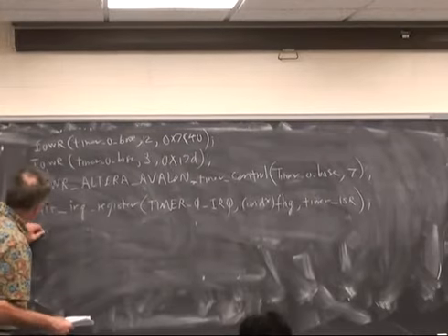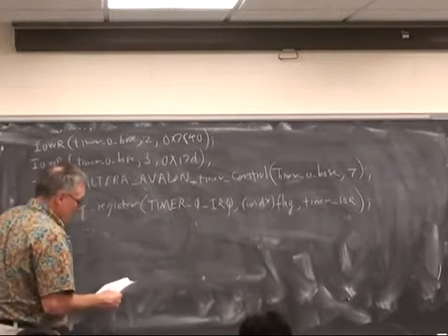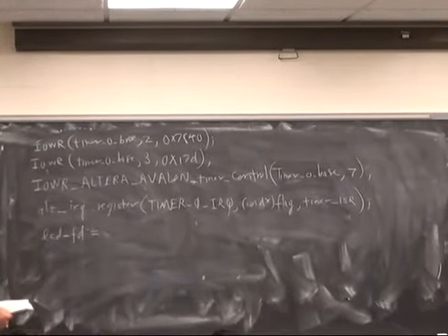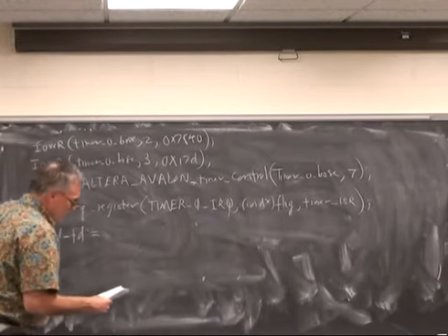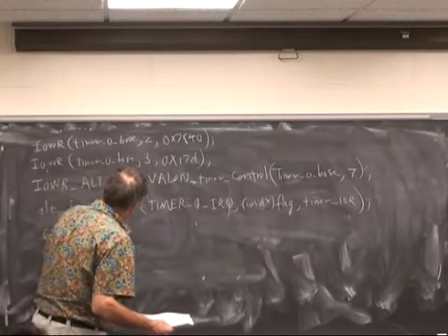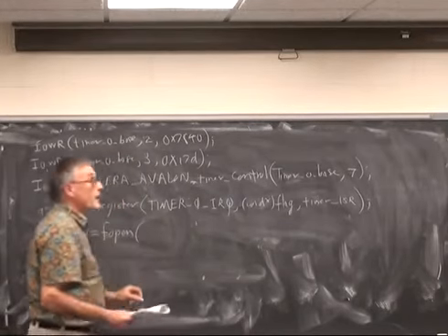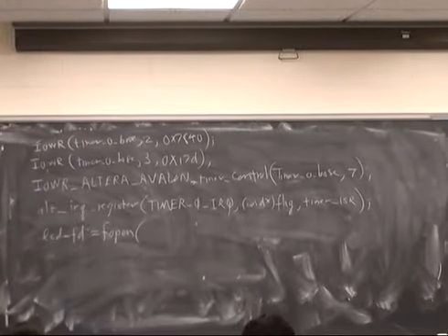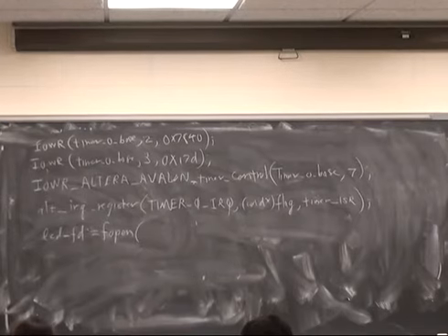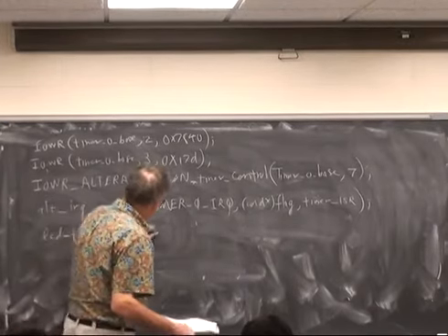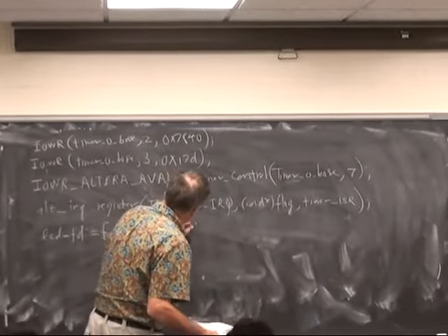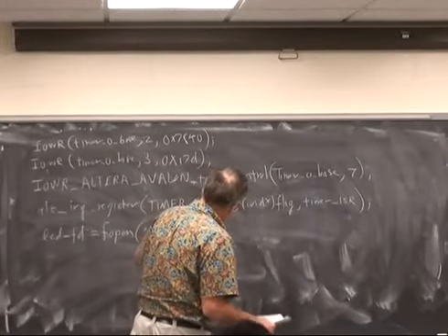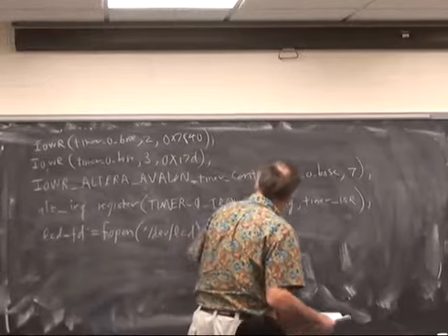And then we have to define the device file, the file descriptor for the LCD, with fopen. Fopen acts as if it's a Unix file open, but there is no Unix operating system. So we give it a device, /dev/lcd, and we're going to open it for write, so we have to specify that.